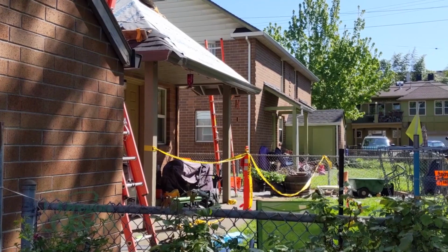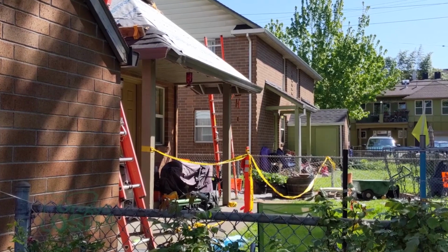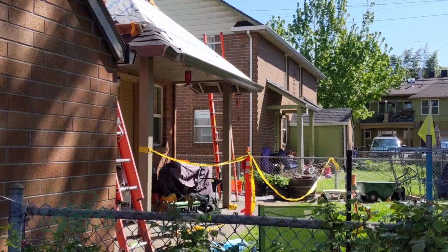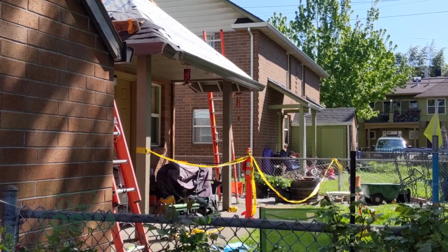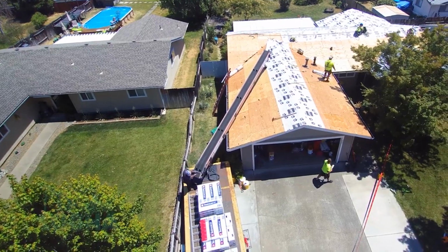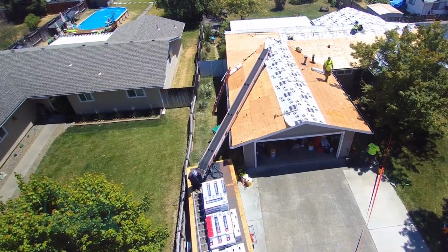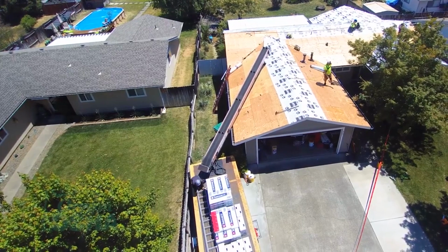As part of that proposal, he takes into account the time it's going to take to set up the safety lines, set up fall protection, tie-off points, whether we need to set up protection for the public. If it's a residential apartment complex, something like that, and you've got multiple tenants, then we will set up safety perimeters on the ground so that the public can't walk into those areas where debris is getting thrown. But then most importantly is when we set up for the crew, when the crew goes up on the roof and they set up their fall protection, put in those tie-off points. So that's all part of that estimating process that the estimator goes through.